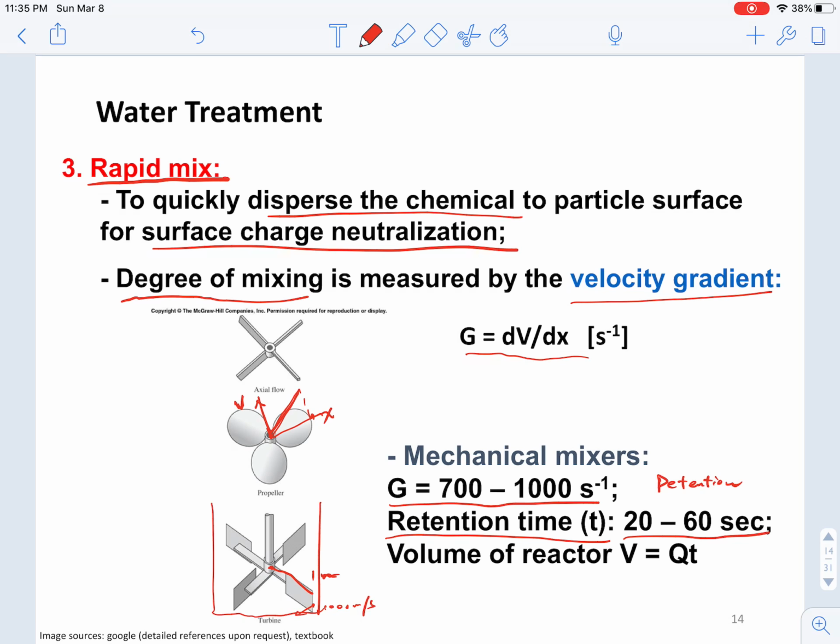So how does this time affect the design? For each tank, there will be a flow rate associated with the processing. The higher the flow rate, typically the longer the retention time we need, to guarantee better mixing of the water. This involves the design of the tank or reactor. If we have the retention time of the reactor, then we can calculate the volume. The volume of the reactor is simply the flow rate going into the reactor multiplied by the retention time.